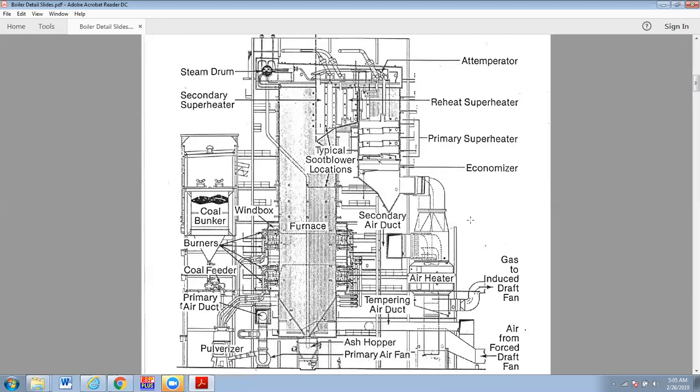And so the low NOx burners and furnace designs are to do what they call staged combustion, which is to stretch out the addition of oxygen to the point that we finally do burn the fuel pretty much, but we do it in a lower temperature environment, which limits the NOx formation. So we don't have as much to clean up after we get the gases out of the boiler.